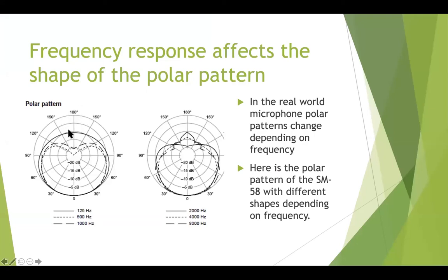The bad news about this microphone with this notch, with this almost circular low frequency response, is that it will pick up things like touching, handling, bass sounds, thumps, booms, bangs from behind, right? So someone would say this microphone is probably susceptible to handling noises and therefore should be in some sort of mic clip, not necessarily in your own hand, all right? Because your hand makes a rumble sound when you touch and move your fingers on the microphone, and this might pick it up more.